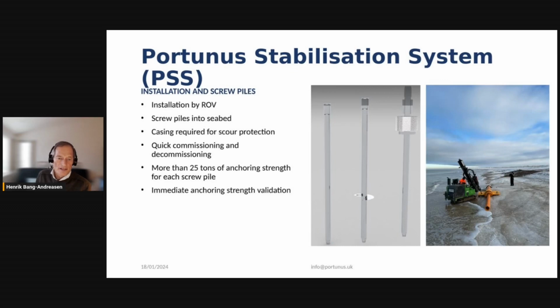So, installation of the PSS and the screw pile mechanism is, again, as we said, with ROV and the screw piles that we actually screw into the seabed, here shown in the middle picture, where we use screw piles that screw into either sandy or at least a seabed that we can screw these into.